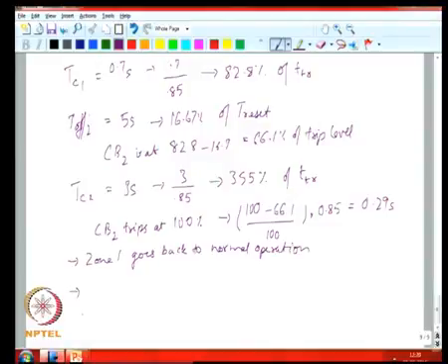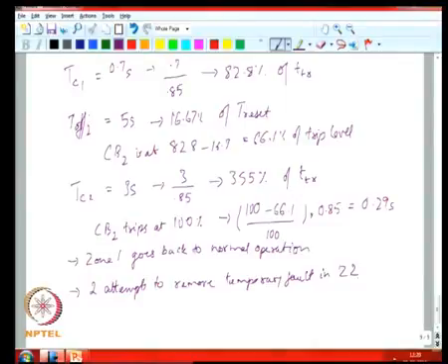what the recloser did was it made 2 attempts to clear a temporary fault in zone 2, and because it was permanent, the breaker tripped before the recloser locked open.